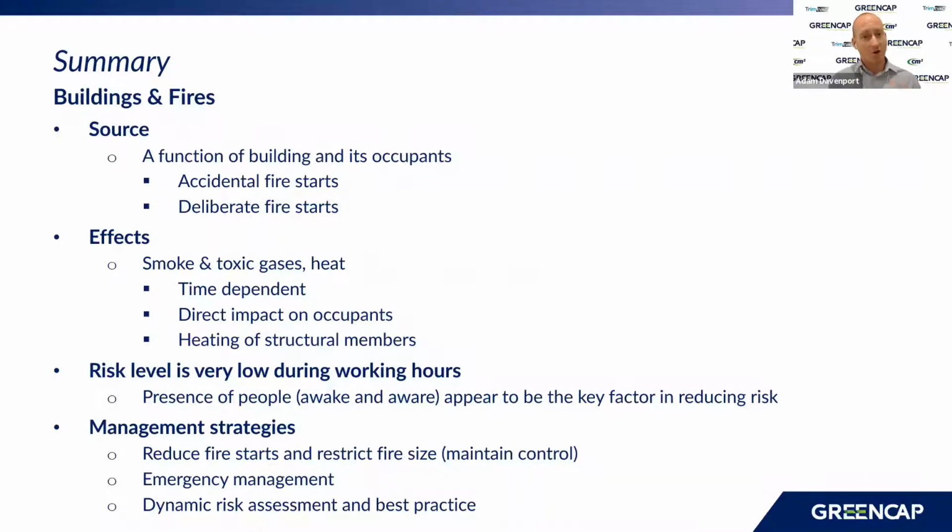We always said, hey, the fire's on the inside. In residential buildings, stay in your rooms, stay in your rooms. Obviously, that wasn't the right call in that situation because the fire was on the outside and can get in a lot faster. So it would have been better to leave. So it's an interesting situation. But if we make sure we educate ourselves, use those checklists, and respond accordingly, we should be able to reduce the risk to any occupants in the buildings.